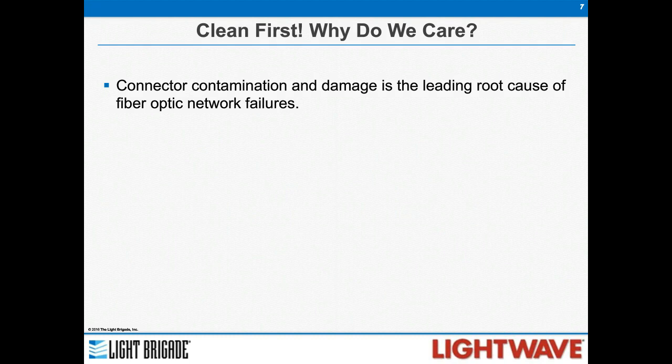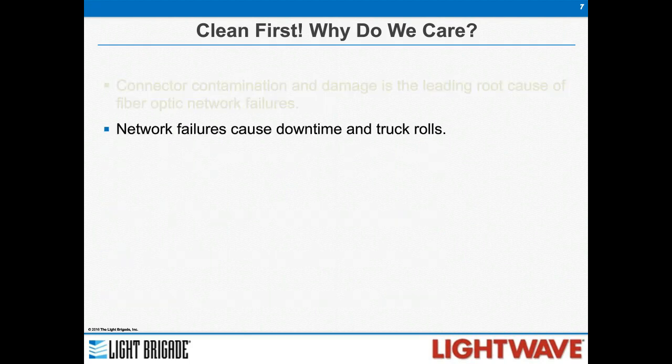But connector contamination or connector damage is still the leading root cause of failures in the field. We've seen studies. Many of us have seen the NTT study that was done years ago, and that may be a few years old now, but things have not changed all that much. When you talk to people who get out there with contractors and installers, they still talk about the most common thing they see is going out to the field, trying to troubleshoot something and finding that someone did not clean their connectors properly and they damaged the end face of their connectors, and you can't recover from that. That's costly in and of itself.